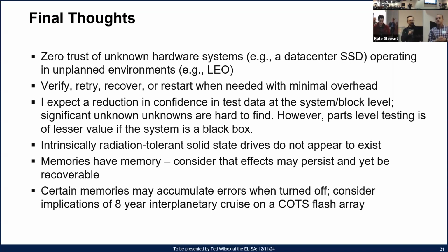Awesome. The last one is, what about large MRAM or non-volatile memory? Yeah, MRAM is great. We've done a lot of MRAM testing. We looked at other folks in the community that are building large systems. We're not at a point where we have terabyte class MRAM devices. I keep hearing about this for a long time, but it brings us to a point where the bit cells themselves are resilient, but you still need all that surrounding peripheral circuitry, because from a purely commercial MRAM standpoint, you may have latch up, something very basic like that, in the CMOS that surrounds the device.